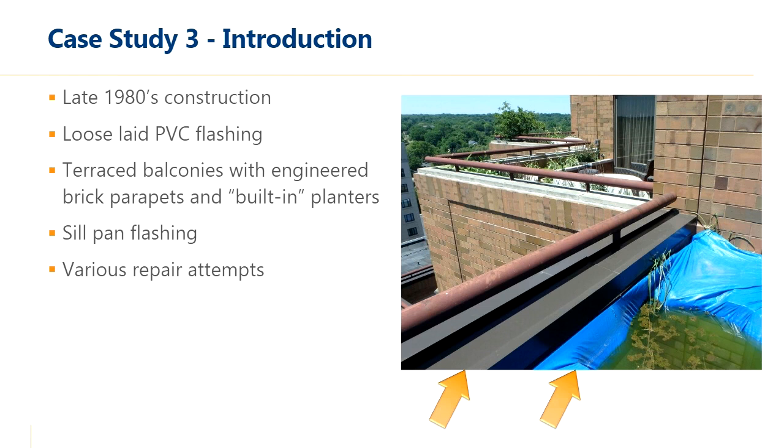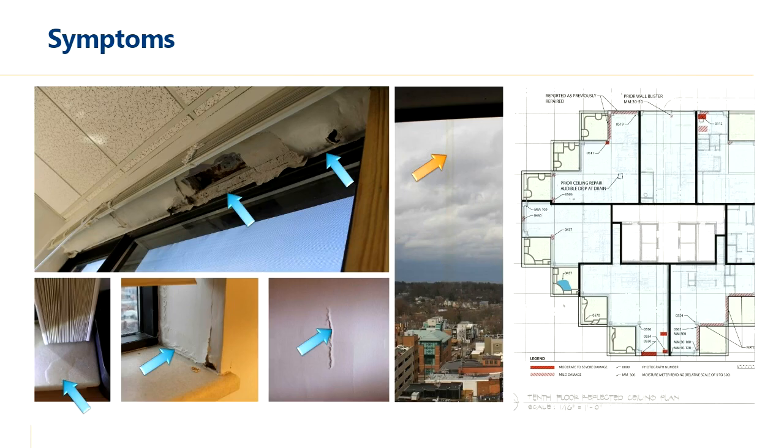So we're going to focus on the wall issues here. Some of the symptoms that we saw at the tops of the windows, at the heads of the windows, the soffit was having some severe distress in locations. They would get water on the interior stools, the jambs, some water damage on the ceilings, and we would also see some streaking on the glass, a rust-colored streak that would occur on the glass.